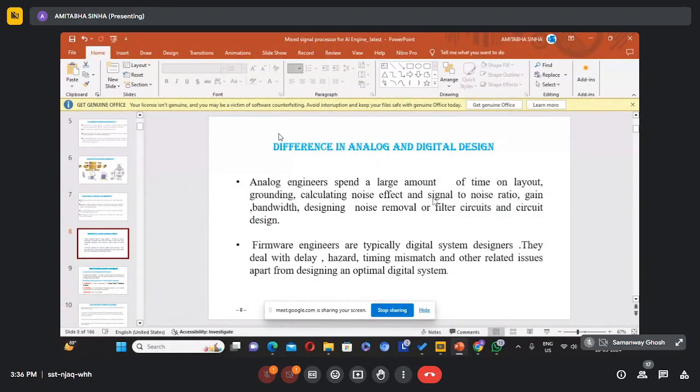it will take some time because the signal has to traverse from the program counter to the memory address register. Some amount of time will be required, maybe a microsecond, but still it is a time. And if it was on at that time, but by the time the signal has entered, it's not enabled, then false data will be entered.